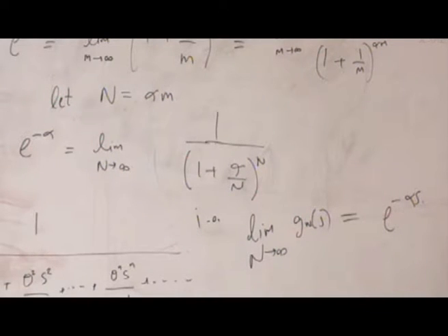So it brings us to the basic fact we are discussing: whenever you add a pole to a system, you are slowing down the response and delaying the system a bit. But as you add an infinite number of first order systems in series, it's an infinite delay.